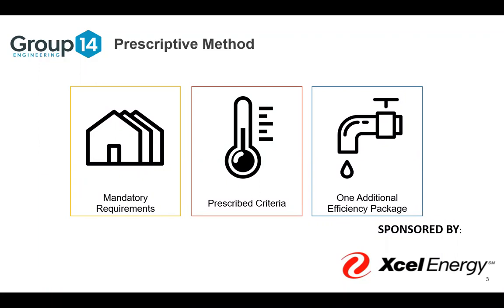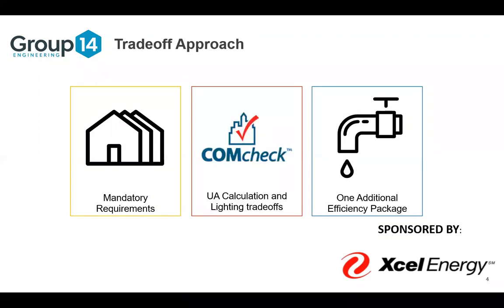When we look at the trade-off approach, you're talking about COMcheck. You still have to meet all those mandatory requirements. Now you can trade off some of the insulation or glazing values within your envelope, that UA calculation. And then we also have lighting trade-offs from space to space. If you were complying just prescriptively, you could not do the lighting trade-offs. You also have to comply with that 1 additional energy efficiency package.